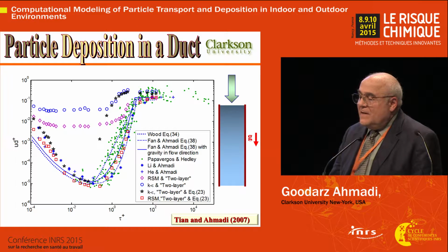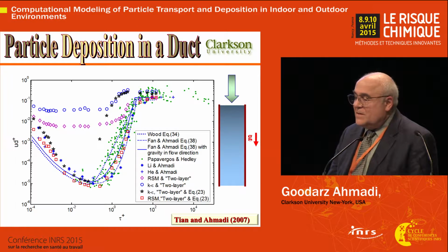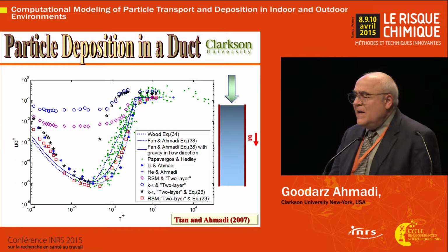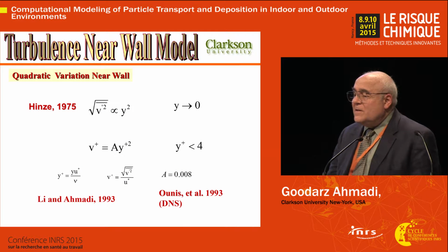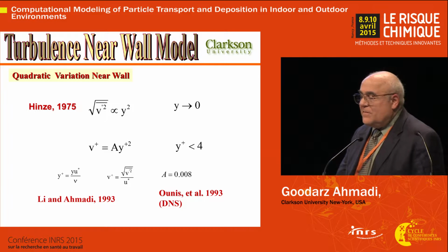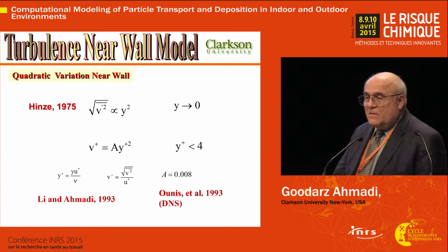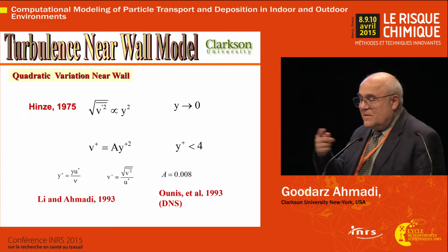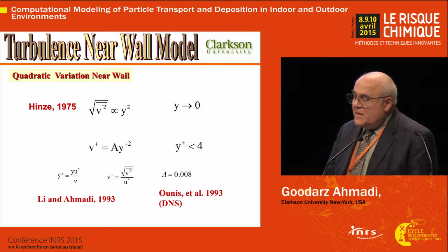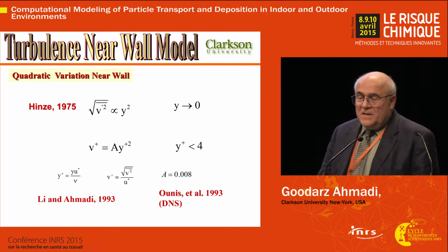Here, basically, we use Fluent as the main medium to calculate the velocity, but use our own code to calculate the particle tracking and deposition. And the key component, actually, we found out is very simple. Very close to the wall, the velocity fluctuation of the turbulent flow approaches 0 with y square. And that's basically because of conservation of mass, that follows mathematically. And the way Fluent calculates, it does a linear interpolation. If you compare the linear curve with the square term, there's a dramatic difference, and that causes some of the error. So by accounting for that, you can actually get a better answer.